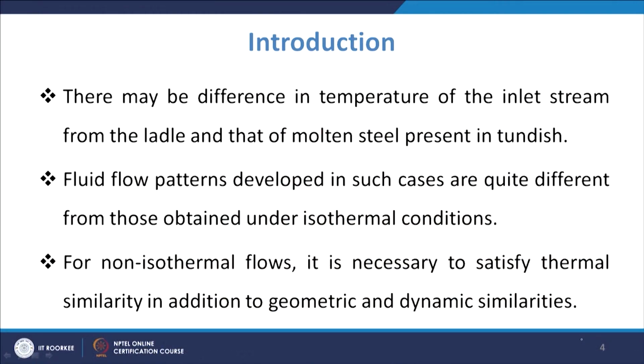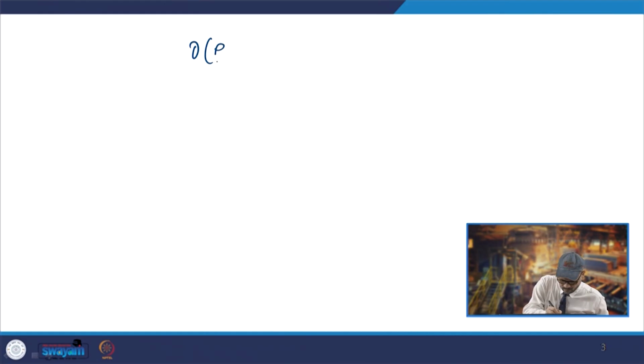So in that case you need to satisfy the thermal similarity in addition to the geometric and the dynamic similarity, and for that you need to see those criteria, how you will manage that. So, if you go for the momentum balance equation for the turbulent flow conditions.